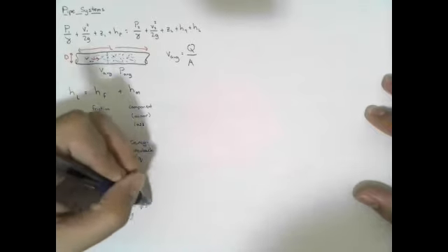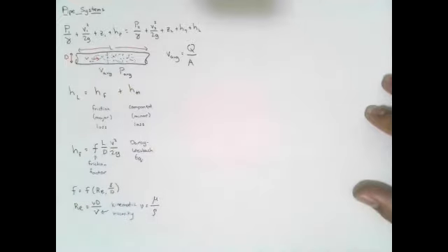And this kinematic viscosity is just your dynamic or absolute viscosity divided by the density of the fluid. You can find values for different kinematic viscosities of different fluids at different temperatures.